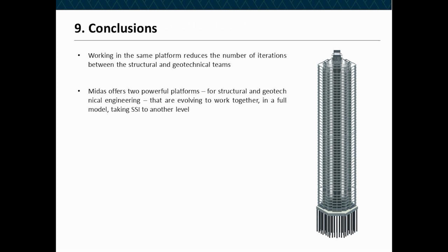Another thought is that we may have reached an excellent numerical model, but it really relies on the information that we input in it. So having a quality soil investigation to retrieve reliable parameters from the soil is crucial. And also having an instrumented pile load test is crucial. So the results of our model all depend on the quality of this information.